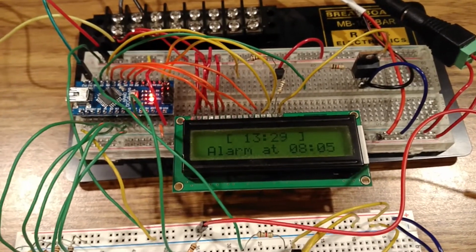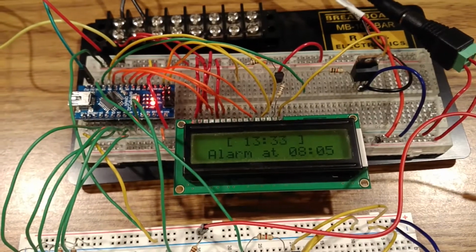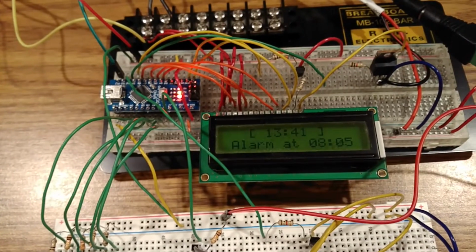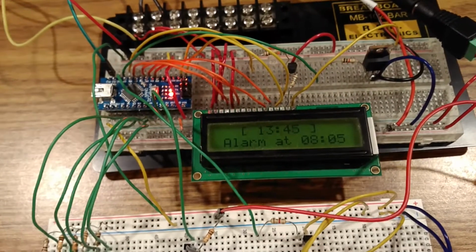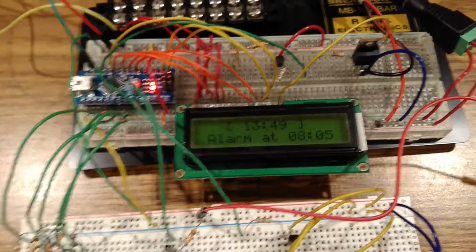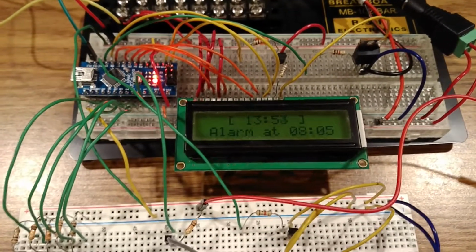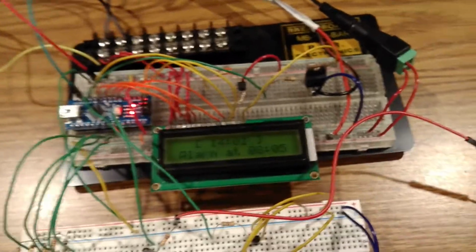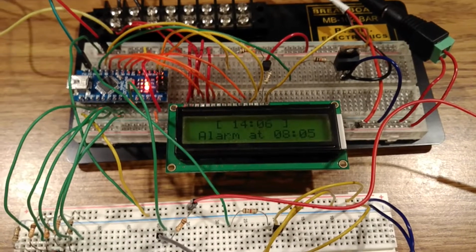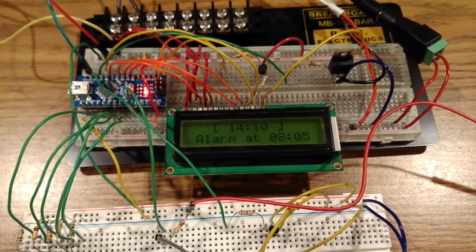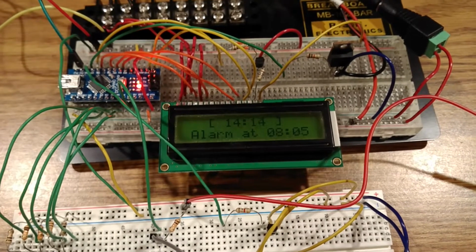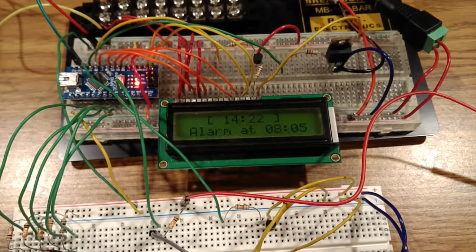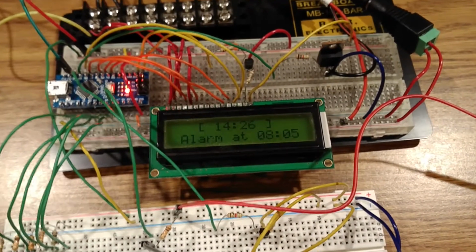So unfortunately, that's something that I could correct with software, but the issue with it is that the ceramic clock is very temperature sensitive, so I may add a software compensation for it, but if I moved it, say, upstairs into the heat, it'll be completely different with the inaccuracies. Maybe it'll be too fast at that point. So what really needs to be done is to use a separate module for timekeeping. There are some standalone timekeeping modules that use some DC batteries in order to keep the time, and they're very accurate from what I've seen.